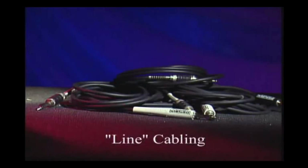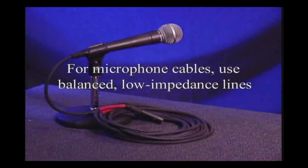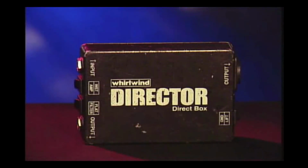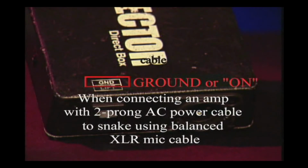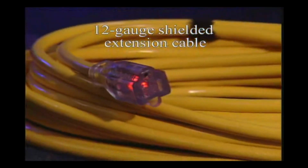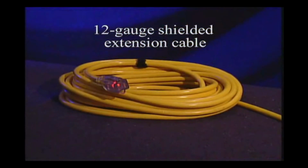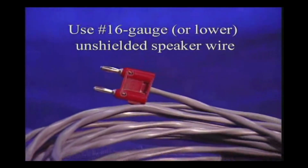The second area of consideration is the cabling used in the audio system. For mic cables, use balanced low impedance lines. With the direct box, the ground lift switch needs to be in the lift or off position when it's used to connect a grounded musical instrument to a snake using a balanced XLR type mic cable. If the stage amplifier uses only a 2-prong AC plug, generally leave the DI switch in the ground or on position. For line level cable, use shielded low impedance cable. For power extension cable, use 12-gauge shielded extension cable. For speaker cable, you can use number 16 gauge or lower unshielded speaker wire.